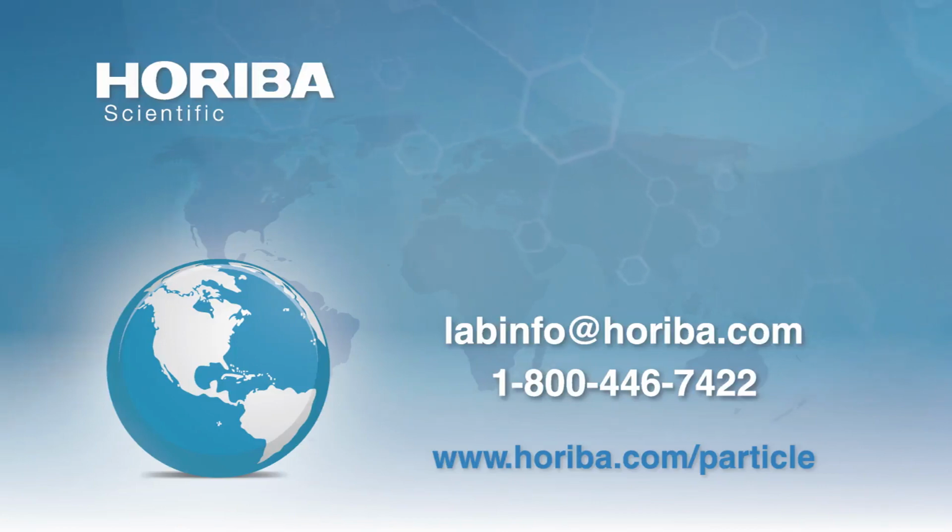Okay, thank you. The second question is, we're facing issues to understand agglomerates and primary particles. Can you share the effect of external sonication on the effect of agglomeration and primary particles? Yeah, this is a very good question because it often comes out when you're measuring particle size. What am I actually measuring? And it happened to me once. Someone gave me a sample and they said, I want you to measure the particle size on this. And so I buzzed it up and measured it and got a nice 2-3 micron particle size and came back to me. And he was upset because he was interested in flocks. He was interested in the size of his flocks, but he hadn't told me that.